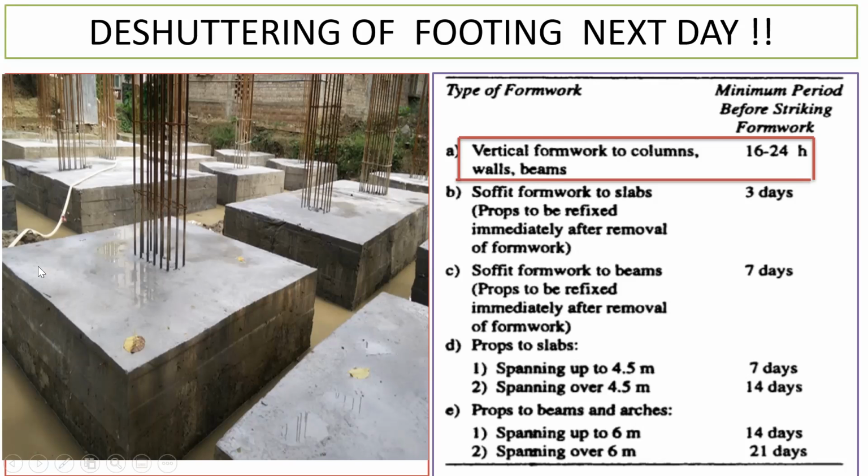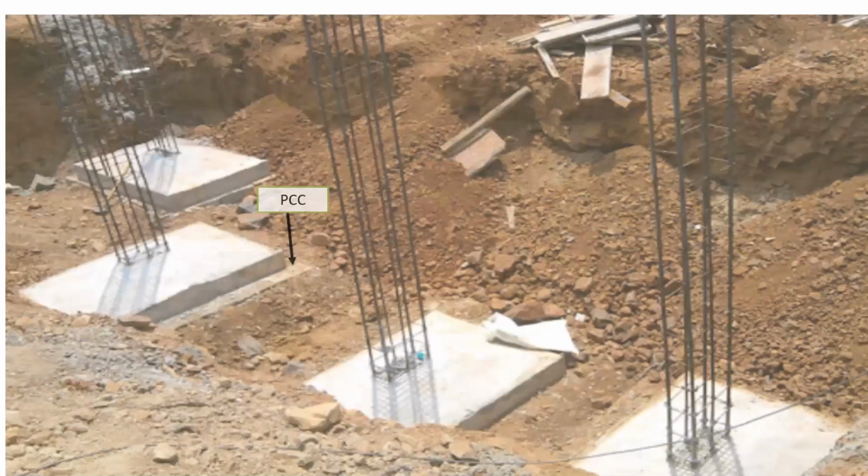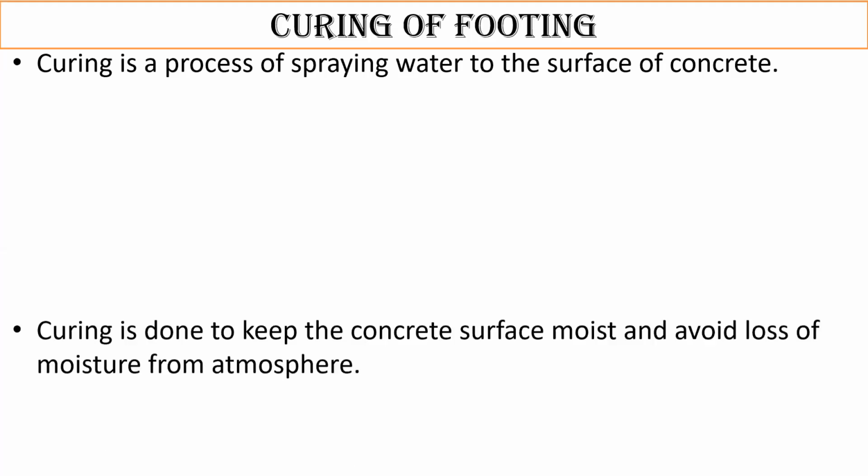Because the water which is inside the concrete, that is to be utilized with the concrete or the cement particles for its hydration process. Only after that, you're going to get the strength that is required. So that is the main idea of curing the concrete.